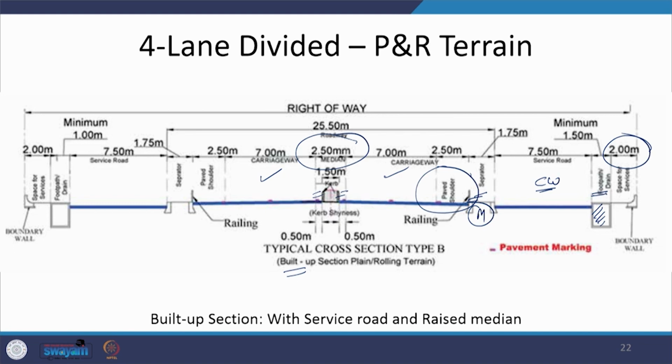Now, this footpath which is being provided along with the drain has a minimum width of 1.5 meters, but then this is to be looked at in terms of the facilities for pedestrians. The IRC guidelines are there, they keep revising. So, kindly look at that before deciding what should be the minimum width that has to be provided. Here in this case it is being shown as 1 meter. So, by mistake it has come, it has to be a minimum of 1.5 meters as talked about on the other side, but now it has been increased and now we are talking about 2 meter wide footpaths.